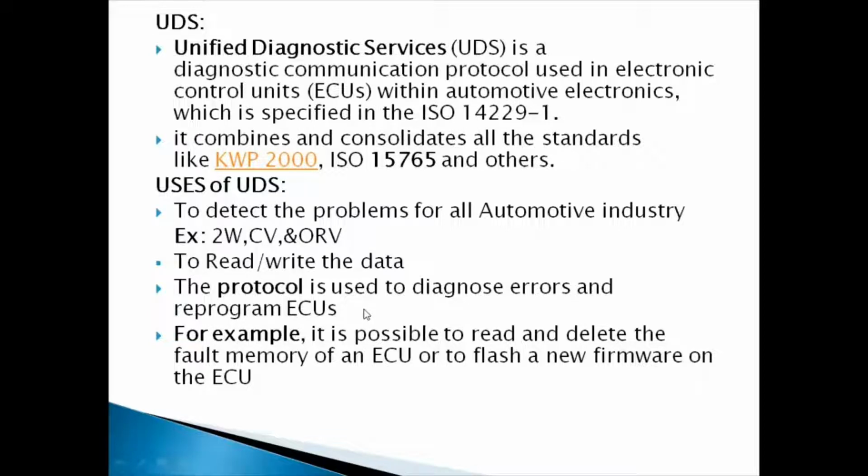Reprogramming the ECU is nothing but, if you have software, right? We have two softwares. One is the old software and one more is the new software. Wherever changes occur according to the customer requirement, we implement them in the new software. At that time, by using this service ID, we flash the new software. We erase the old software and flash the new software. How is it done? We have some tools like DET, Diagnostics Engineering Tool, or depending upon the organization, the tools may change. So there we select that tool.